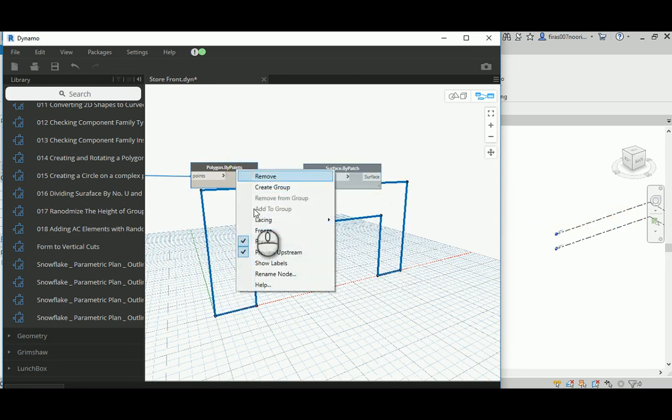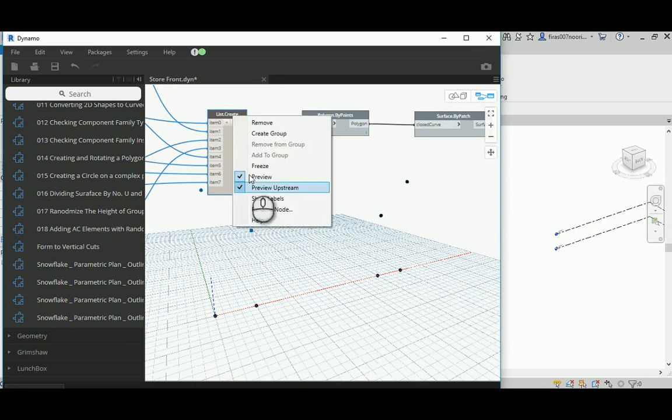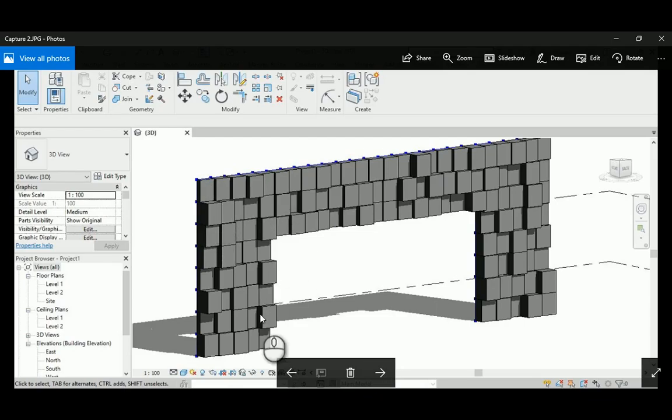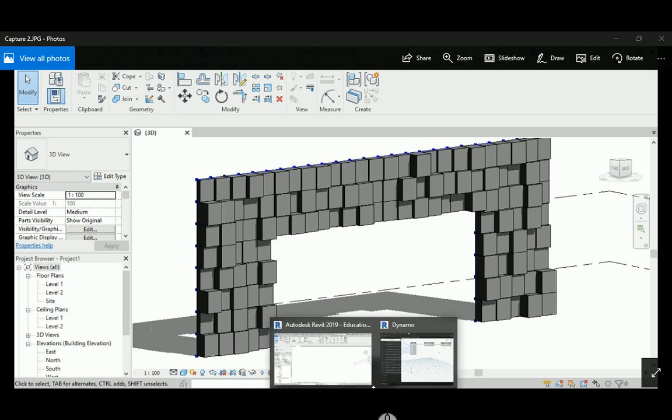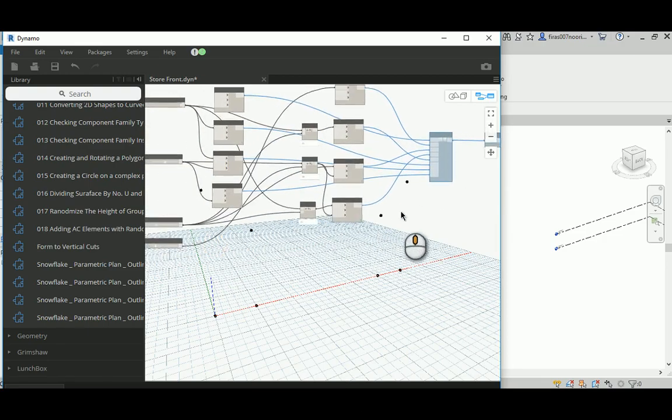which is basically we need to, again, turn off this one. We need to create or divide that one surface, or divide that geometry, into 3 surfaces. That's 1, that's 2, and the one in the middle, which again requires us to create 2 extra points.